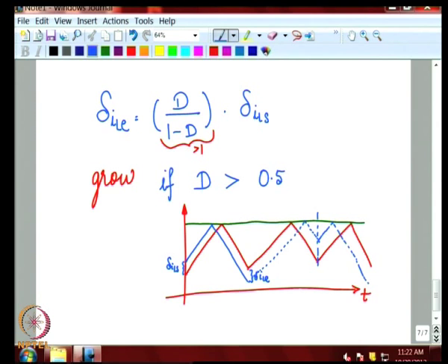You can recognize that this is an unstable situation, which will lead to pulse missing and incorrect inductor current wave shape and incorrect current programming.